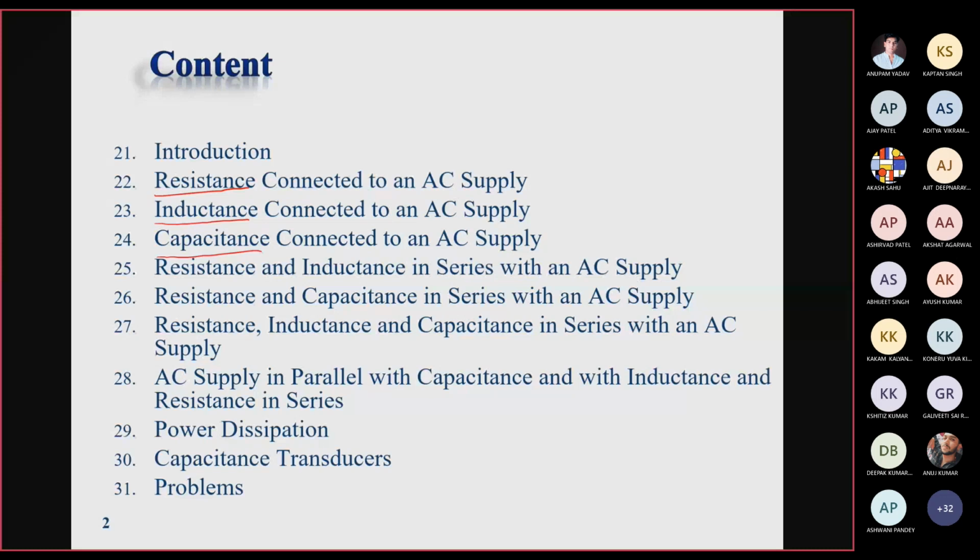So normally more than 90% of the loads available in our electrical system are of inductive nature, right? An RL load, a mixture of resistor and inductor. So most of the loads are inductive in nature. Whatever you consider, practical examples you may consider as motors, AC motors, whether it is a single phase induction motor or three phase induction motors. Then you have the fan installed in our households, AC, fridge, whatever the load you see. So most of the loads are inductive in nature.